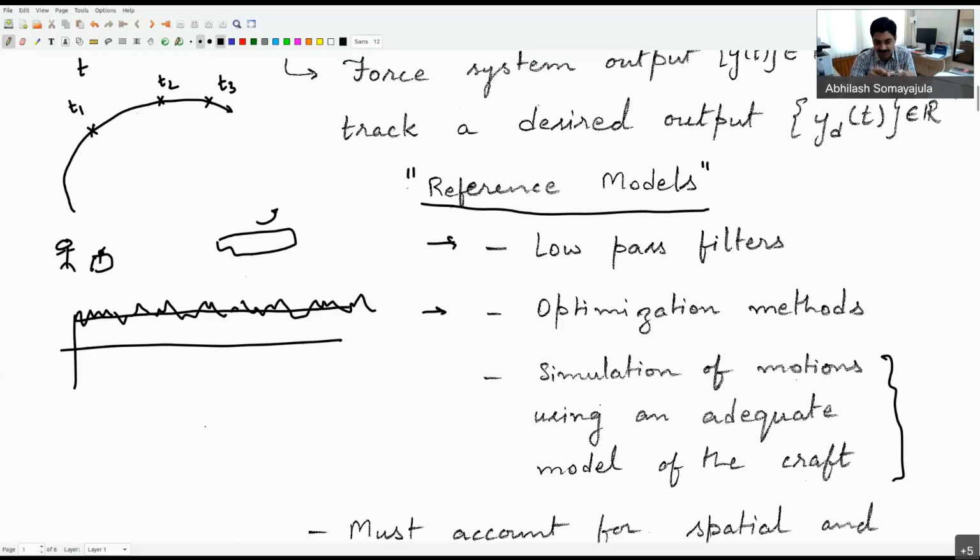If you are looking at our small-scale boat, you would be right that the joystick is more like a controller, because in our craft I've taken the joystick commands and directly adjusted the control voltage for the motors. So when I move my joystick, the control voltage to the motor automatically changes.